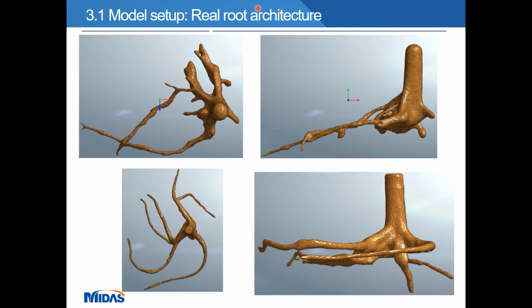We use Bishop stress, and we also managed to incorporate the change of Young's modulus due to matric suction. This is an approach presented by Rojas. In this condition, we try to capture how the elastic modulus changes with matric suction during a rainfall event. So we will see some results in this case.